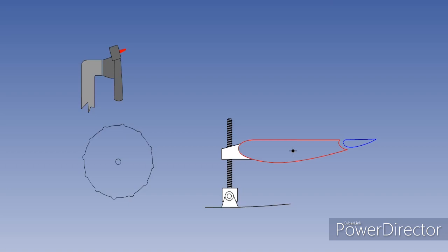There is also a warning light that illuminates to tell the pilots that the trim is running, and on the Boeing 737, which has exposed trim wheels, their clanking noise when rotating will be an unmistakable warning. If the stabilizer trim does run away, all inputs to the screw jack drive can be removed by emergency shut-off switch action on the flight deck.